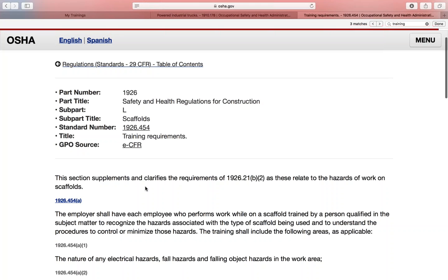So let's talk about a few things, folks. I'm going back to page 27 now at the bottom right. And the following list of requirements that we talked about: understanding the associated hazards in the manual, understanding all the procedures and warnings, being familiar with OSHA's work rules and OSHA's requirements, and then demonstrating that they understand how to operate the associated personnel lift or aerial lift, which is exactly what we were just talking about, okay? And that covers what we just talked about on page 27.